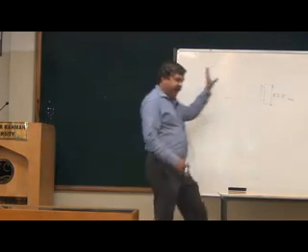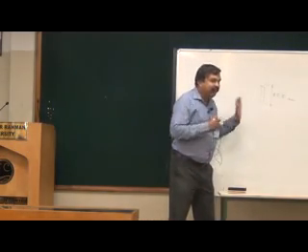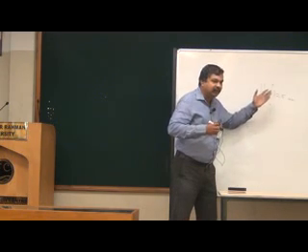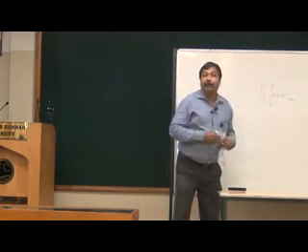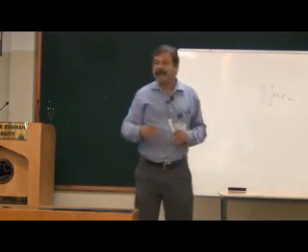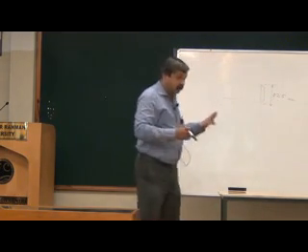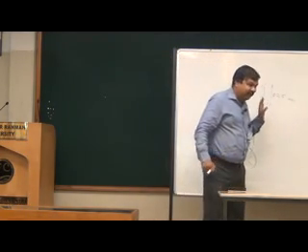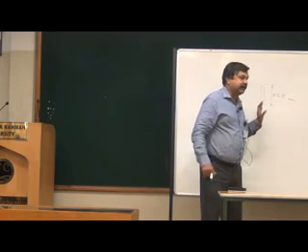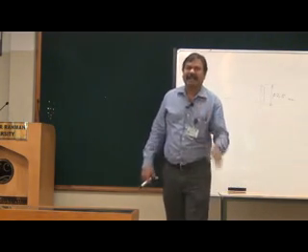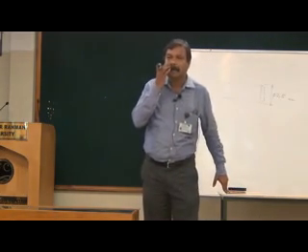If I give a design in which I just say the diameter of the shaft is 25 mm, people will throw it back to me, because the manufacturing engineer will tell me that there is nothing called exact 25 mm.